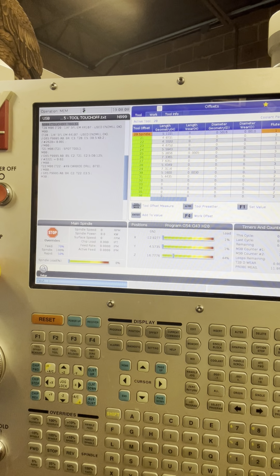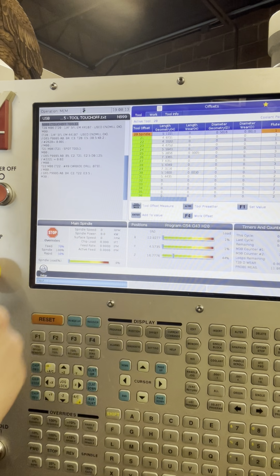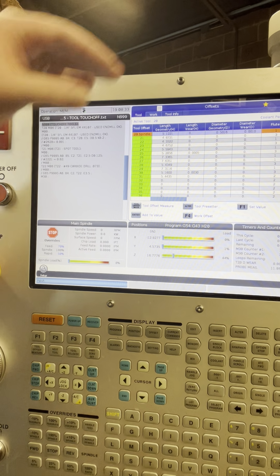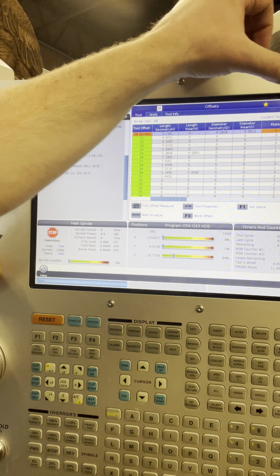There, on our machine, we have a programmable coolant nozzle, and that has a number similar to this. That's why I was trying to go to 0. So it goes from 0, I don't know the highest number, but basically it zeroes it out every time. I'll have to set this up if you guys need to do this, but we took our shortest tool and our longest tool, and I got a linear equation, and then in this touch-off routine at the very bottom, I take this number for the height, run it through that equation, and it gives me where to aim